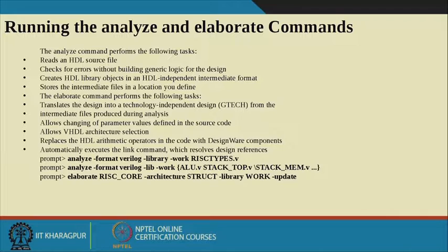By writing analyze -format verilog with the library name work, with the corresponding Verilog file risc_types.v. Here in this command, analyze is the command I am giving. The format is Verilog.